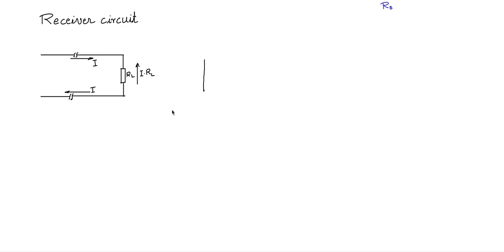So let me process it using an op-amp. In the op-amp, I'm going to write plus and minus. You would have studied the differential amplifier, or the difference amplifier, which gives the difference between the two voltage sources at the plus and the minus side. So let me draw the topology of a difference amplifier, which is very similar to the non-inverting amplifier and inverting amplifier both put together. There is a voltage divider at the non-inverting end.